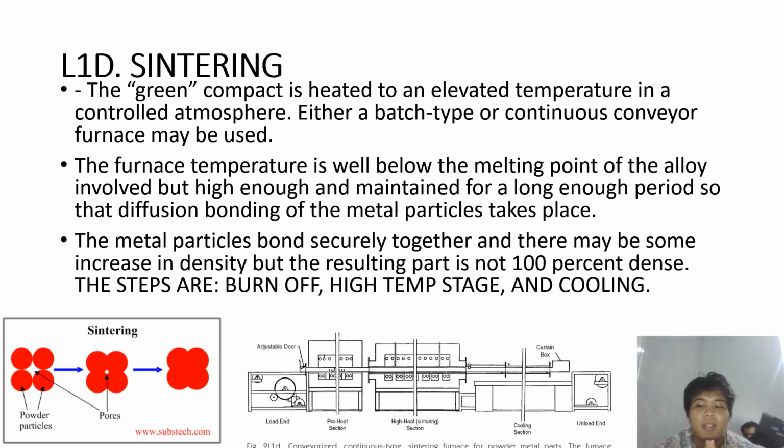The metal particles bond securely together and there may be some increase in density, but of course it's not 100% dense. The steps: burn off, remember? High temperature stage and cooling. So it's burn, holding at high temperature and then cooling. So this is the point of sintering, making the powder particles, from spacing or pores or volatiles, into a solid one. So this is just the process.